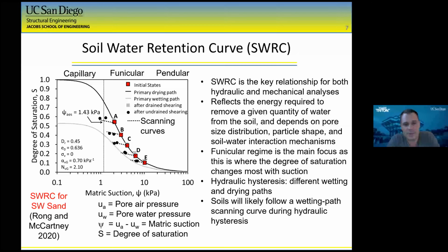One of the key variables that we're going to be using in our constitutive model is the soil water retention curve. In this relationship, this is quantifying the amount of water in the soil for the amount of energy that it takes to withdraw the water from the soil. In this capillary regime, the soil is still close to saturated. In the pendular regime, your soil is pretty much dry. So we're really going to be focusing on this funicular regime where there's a large amount of change in degree of saturation with changes in suction.